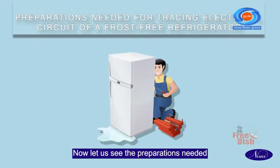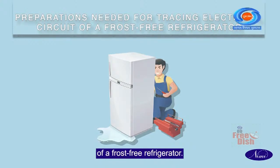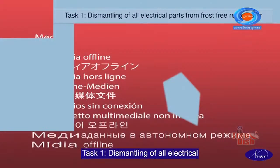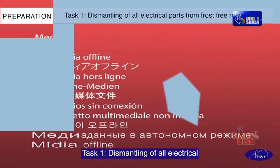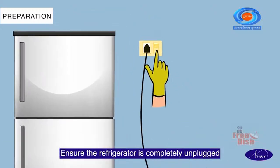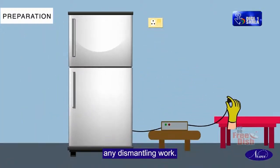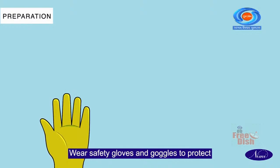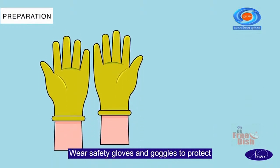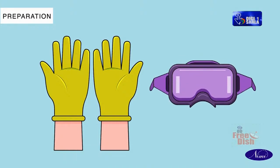Now, let us see the preparations needed for tracing the electrical circuit of a frost-free refrigerator. Task 1. Dismantling of all electrical parts from frost-free refrigerator. Ensure the refrigerator is completely unplugged from the power source before starting any dismantling work. Wear safety gloves and goggles to protect against sharp edges or electrical hazards.